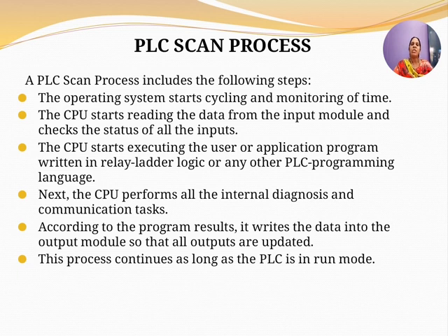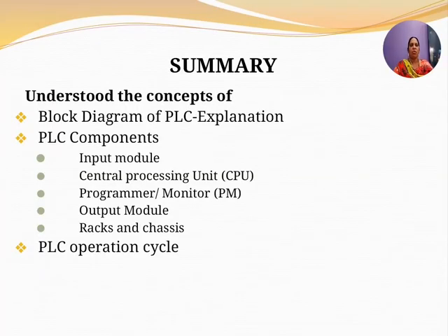This process continues as long as the PLC is in run mode. So to summarize our topic of discussions today, I have dealt with the block diagram of PLC. The major blocks of a PLC, or programmable logic controller, consist of the input module, the CPU, the output module, the power supply, the programming device and the memory. We have the input devices and the sensors, and the output devices and the loads.